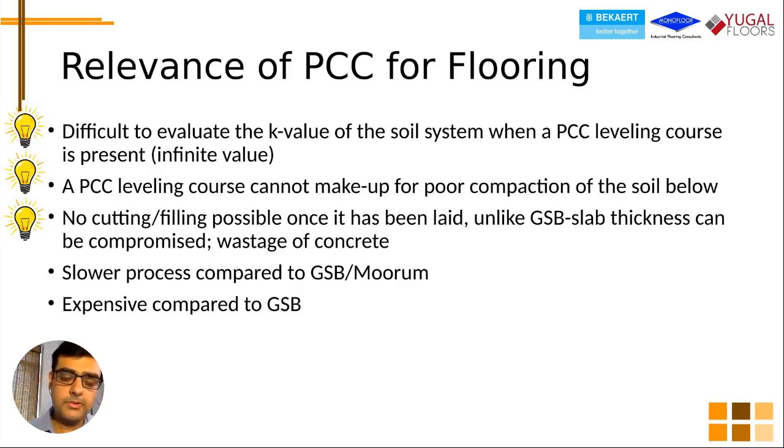All right. Now talking about PCC and its relevance in flooring. This is a very important slide because a lot of us tend to use PCC a lot. First important point is you can never measure the K value of a soil system where PCC has been used, because essentially PCC gives you an infinite K value if you try to do a test. And it cannot make up for bad compaction. If the soil below the PCC is not compacted well, your sub base or your floor is bound to settle down. PCC is not going to offer you any extra protection against settlement. Most importantly, no cutting or filling is possible once it has been laid.